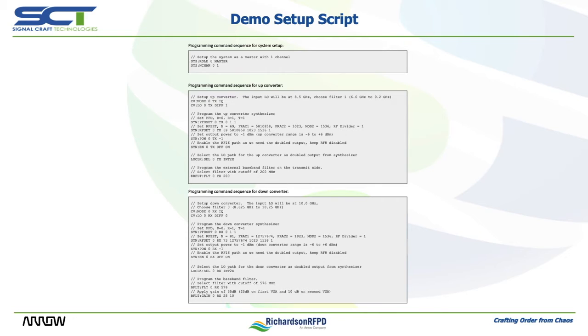Therefore, the command needs to be directed to a specific address. The next argument is the characters TX, signifying that the up converter, as opposed to the down converter, is to be selected. Finally, the argument IQ is used to direct RadioThorium to automatically set the switches, filter paths, and programmable gain registers required to support the IF input.